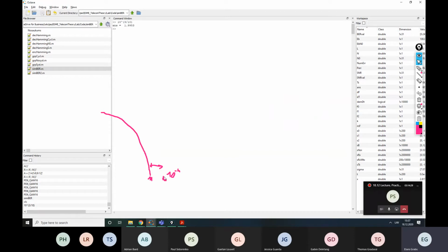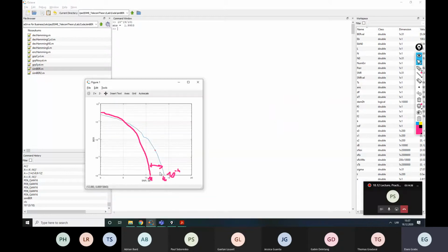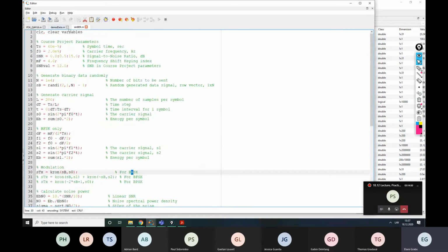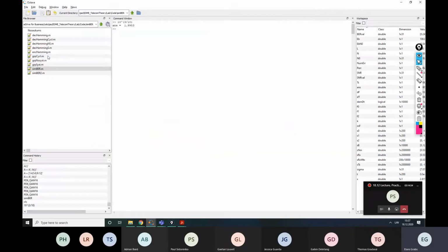So 3 decibel almost means that you can have twice as weak a signal if you use coding and still have the same error probability as before, which is a lot, right? So basically, we are going to test this thing out. For that, we need to work with this program, BER, and additionally with these two files you have downloaded.